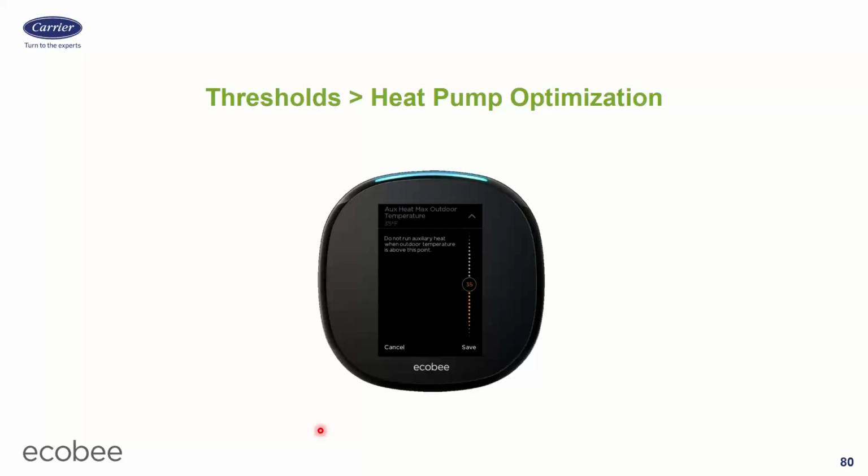I can also lock out the auxiliary heat at a certain temperature. So my heat pump is going to be sized for cooling typically, which means I'm not going to have enough heat in our market. I'm going to have enough heat when it's like 40 degrees outside, and I might have enough heat when it's 22 degrees outside. But at some point, I'm not going to get enough heat out of that heat pump. And it's very dependent upon the model of heat pump that I have.